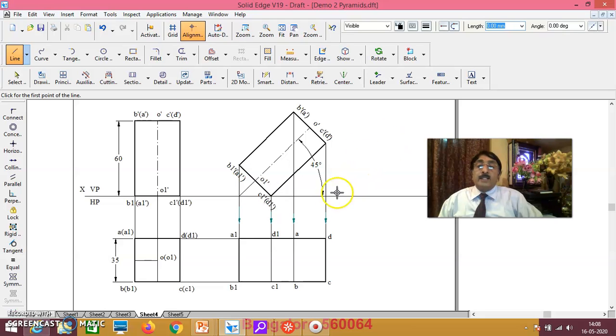Now, since top surface and bottom surface are same in projection of prisms, you compare top surface with bottom surface. Whichever surface is nearer, darken it. Immediately, remaining edges of the other surface, make it dotted. That means here, when you're looking from the top, perpendicular to HP, top surface is nearer, darken the top surface.